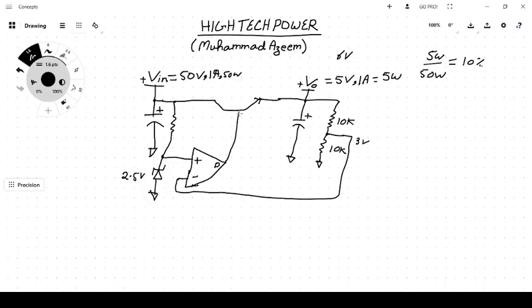So the supply voltage to the base would be reduced, and due to the reduction of base voltage, the saturation of the collector emitter would be reduced, and there would be a much higher drop across the collector to emitter, because it is now trying to turn off.